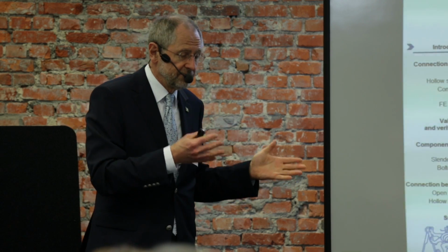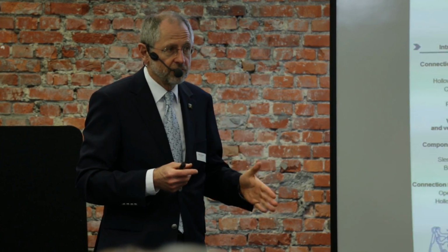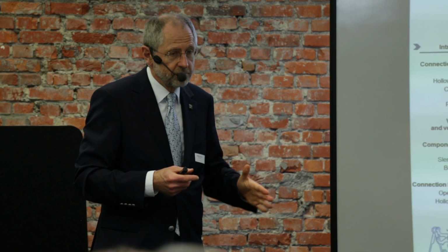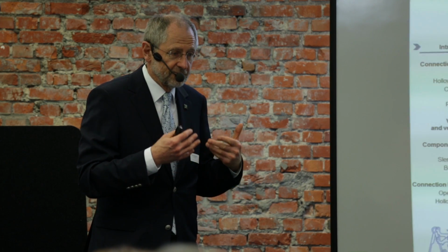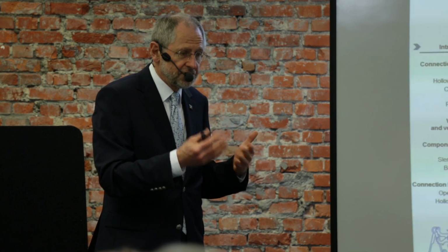But with informatics and with full description, we are going also for stiffness, and we have initial stiffness, which is completely different from the safety point of view, because it only initiates the distribution of forces, and it's like the modulus of elasticity for material, and so we do not need so much accuracy, and we do not need to have a safety factor on it. And then there is the deformation capacity. On the deformation capacity, I would like to go a bit further.